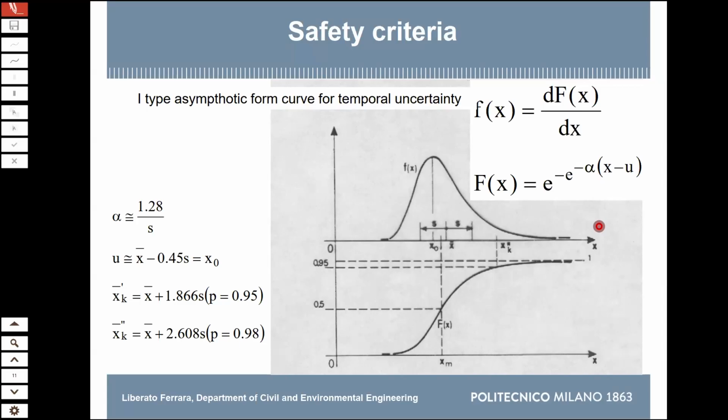Because what you get from the lab is an average. And then from the average, you have to go back by a certain coefficient, as it's written here. So the log normal, we are not using the log normal because it's better or gives us advantages. It's because the experimental results of compressive strength of concrete appear to be distributed like that.